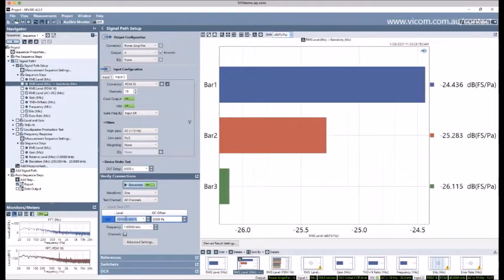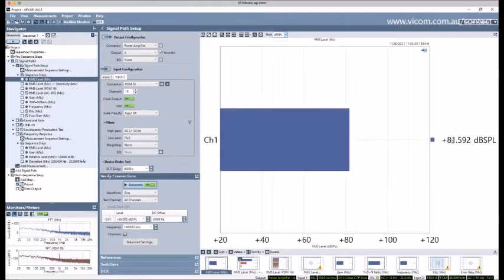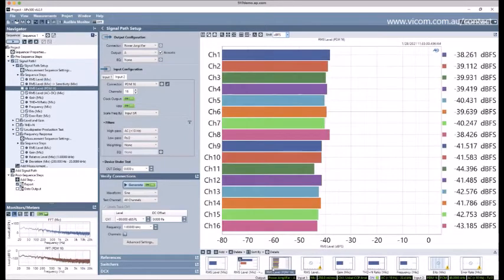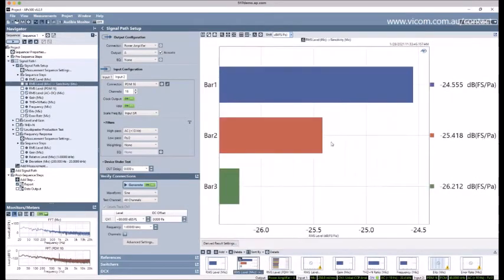So for example, let's crank our sound source down a little bit. You'll notice now we're measuring 80 dB SPL at the reference microphone, and minus 38 dBFS at the number 1 MEMS microphone. But of course, the ratio between the two remains constant. We'll take advantage of this sort of natural cancellation of the source speaker when we measure frequency response.